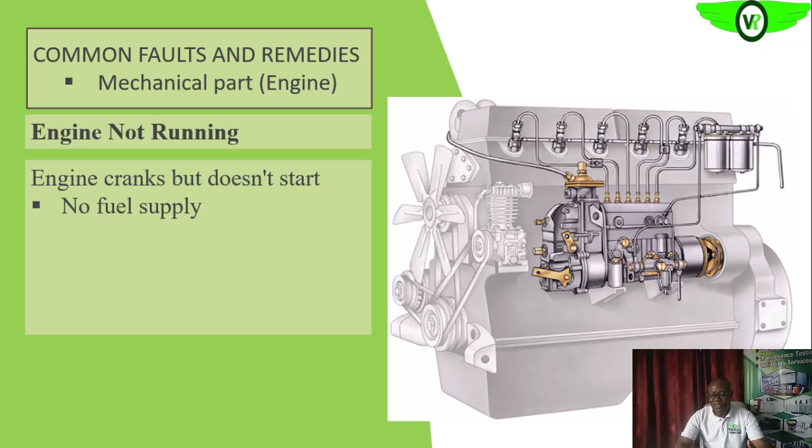Or the pump itself could be faulty. Or there is no fuel in your diesel tank. All those are situations that can cause no fuel supply, and once there is no fuel supply, the engine will not start.